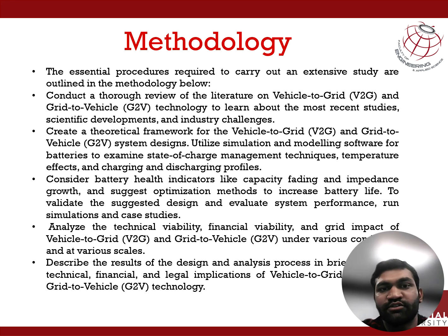design the system, and then we try to implement it in simulation modeling software for the batteries and examine state of charge management techniques, temperature effects, and charging and discharging profiles. Consider battery health indicators like capacity fading and impedance growth, and suggest optimization methods to increase the battery life, especially for the electric vehicle, where the battery is the heart of the electric vehicle.